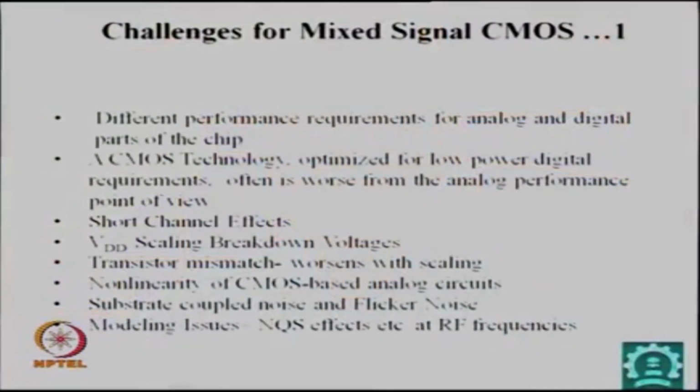So-called non-quasi-static effects: those who have learned the devices course from me, hopefully, we keep telling you that all the analysis is steady state or thermal equilibrium. In real life there is nothing called steady state, it is non-quasi-static, and since it is non-quasi-static, there are huge problems in modeling. If you do not correctly model at those RF frequencies of gigahertz and above, you have more problems in design, because what you thought was correct is not at all correct, and then the chip will never work to the specs you are looking for, or may not even work. So that is the major worry of a designer in the mixed signal area.